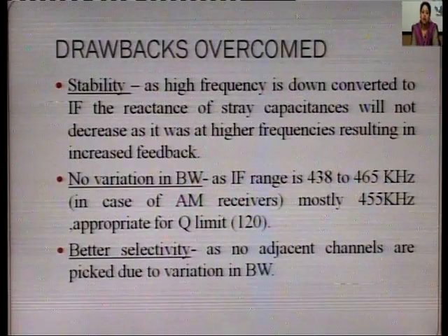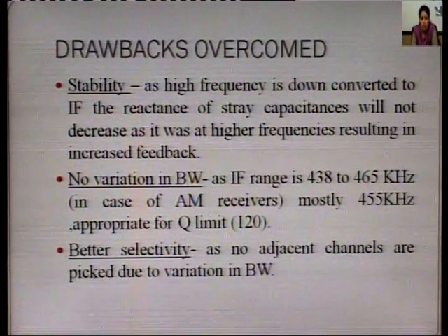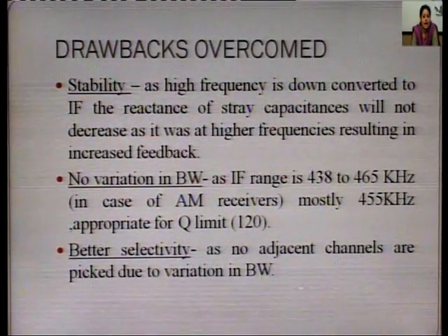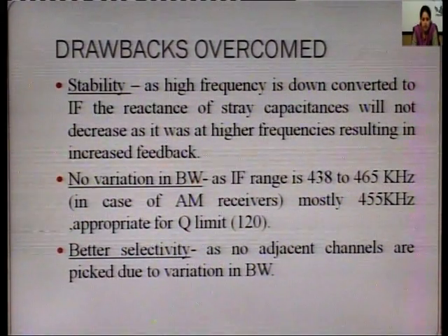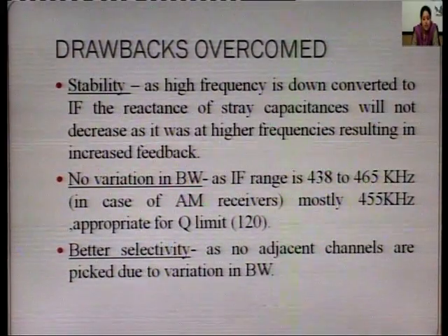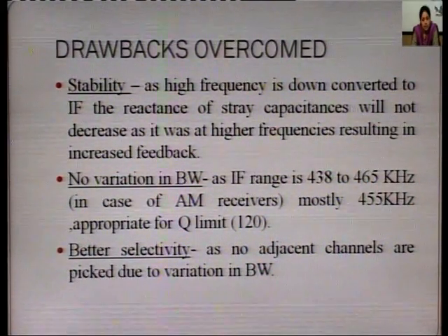Now, how are the drawbacks overcome in the superheterodyne receiver? Considering the first drawback of the TRF, that was stability. As the high frequency is down converted to the intermediate frequency, the lower frequency, the reactance of stray capacitances will not decrease as it did at higher frequencies, which resulted in increased feedback.